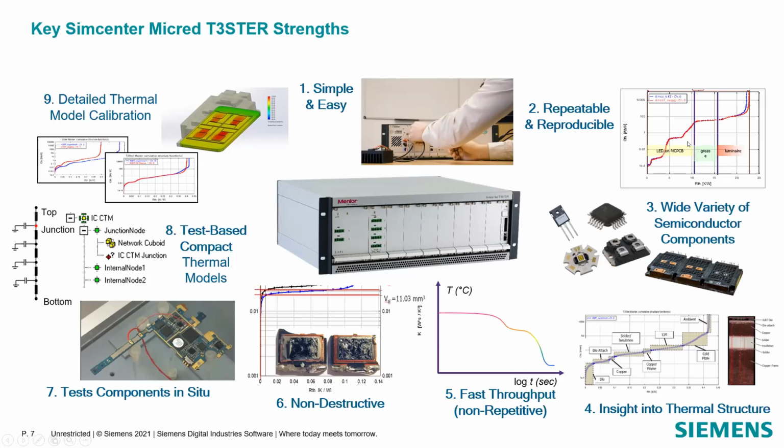The measurements are highly repeatable and reproducible. So no matter where, with which equipment you are trying to reproduce the test, in the same thermal boundary conditions, you exactly get the same results. And that allows structure functions and this entire technology to be used in a supply chain to communicate thermal information.